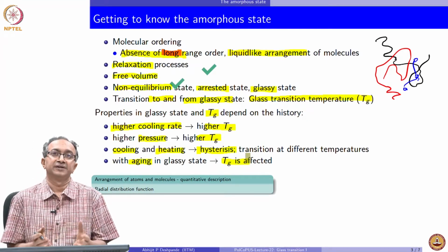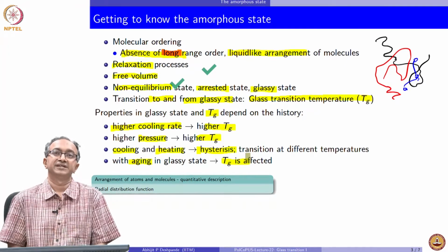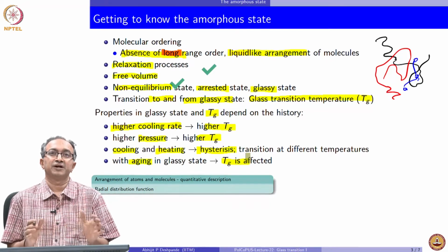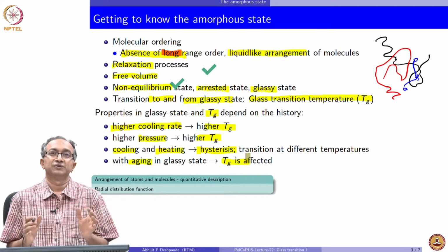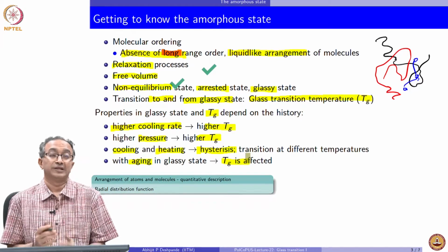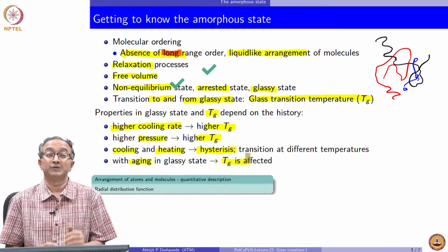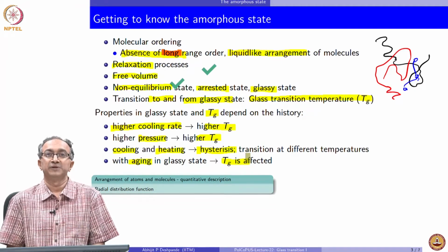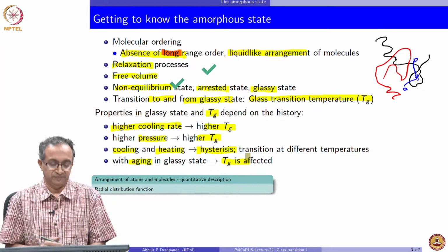So, for example, in aerospace applications, if glass transition is around 170, 180 degrees Celsius, we go ahead with the design and say that any time the part should not see temperatures around 120 degrees Celsius or higher. So, with such things, we know that we are sufficiently away from glass transition temperature while the part is serving, so that any of these relaxation processes, aging processes will be minimal. The effect of these on the properties of the material will be minimal, and therefore, we can assume constant properties and do our engineering design.